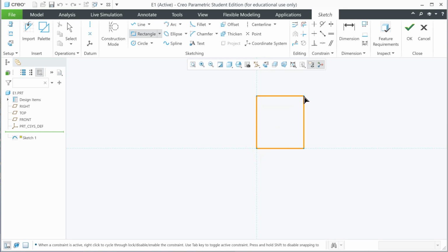So just click, and you can see as we're dragging this out, you could just visualize what you want there, maybe about that size. Click, and now hovering over this area, go ahead and click on the middle wheel. If you have a wheel on your mouse or a third mouse button, click on it like it is a mouse button one time, and the dimensions should appear. And now you can drag those dimensions out. You can see we have them there.